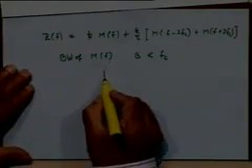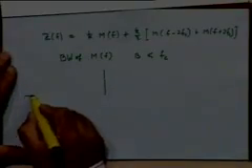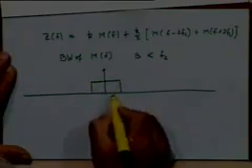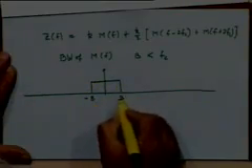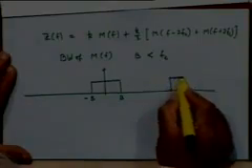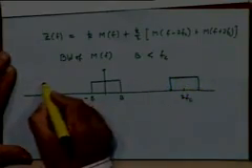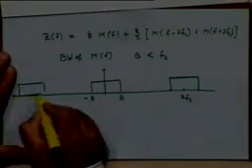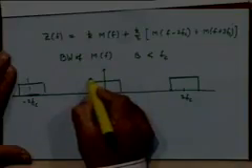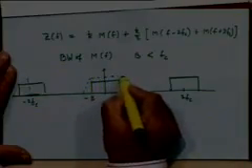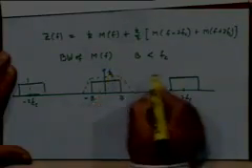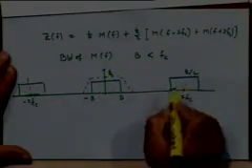So in the frequency domain, the Z of f will look something like this. There is a desired component from minus B to plus B, and this part is around 2fc, and this part is around minus 2fc. This amplitude is k and this is k by 2, which is not reflected in this diagram.